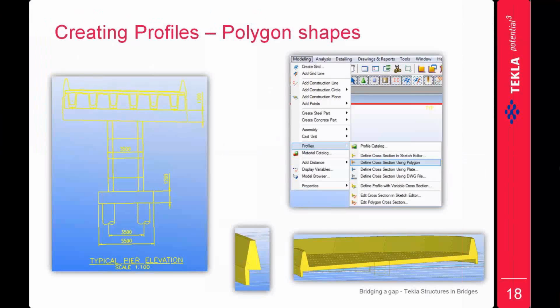And when creating the profile, different options are available, like using the sketch editor or using the polygon. We can bring in a DWG file also here as sections. Those are going to be the fixed profiles, and the rest are the parametric profiles, so that anytime you can change the concrete sizes. Automatically the reinforcement attached to that follows the concrete boundary.